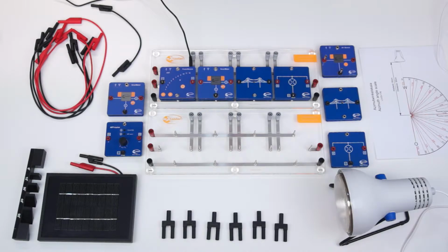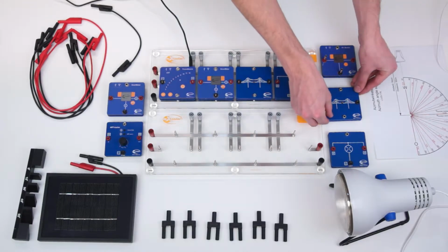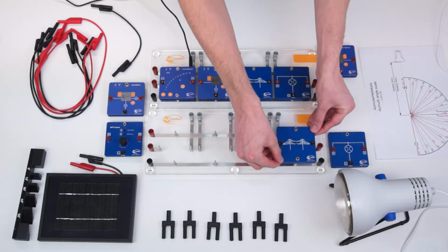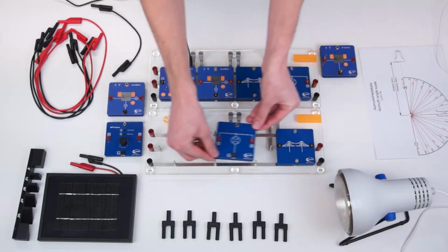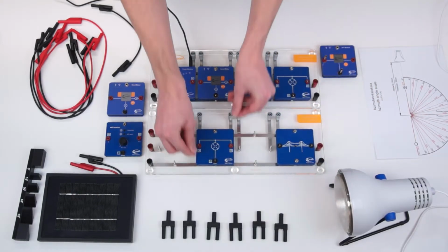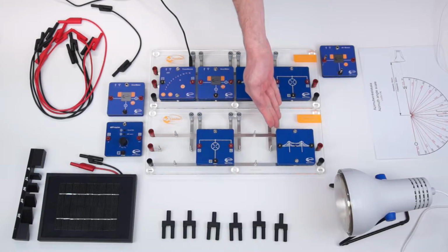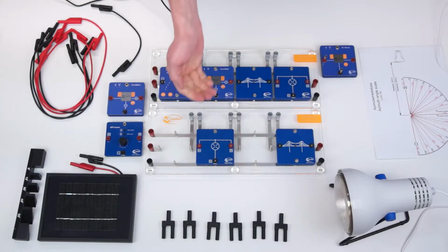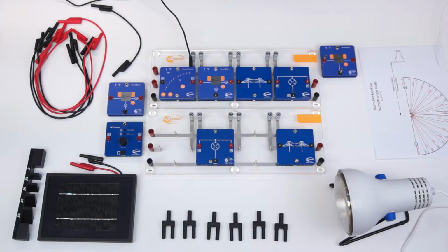For the next section of the low voltage strand, we need the second base unit. It will also be initially equipped with a grid module and a light module. These simulate the line resistance between the 2 houses and the second house. To illustrate the problem of overvoltage, we will install a photovoltaic system with MPP tracker at the second house.